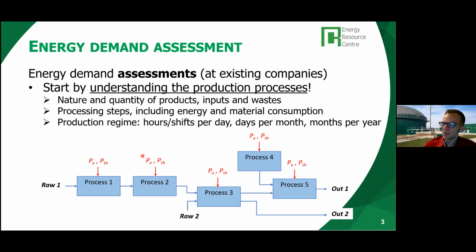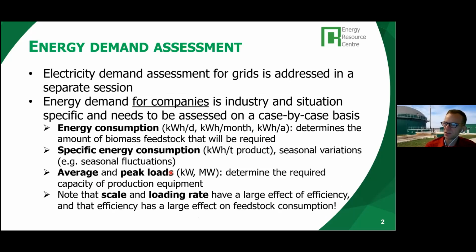Note that I also included the thermal energy here. The previous sheet looks a bit like it's focused on electricity, because I'm using kilowatt hours here, but it also holds true for heat consumption. Heat can also be expressed in kilowatt hours, although more usual would be, for example, gigajoules per hour, per day, or per ton of products, or tons of steam.